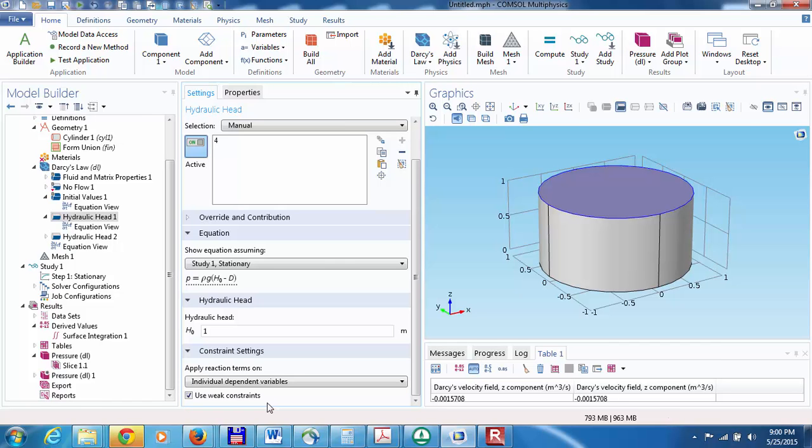On the equations that correspond to the nodes on the boundary where the value is specified to be a given hydraulic head, in this case 1.0, that equation really is not needed in the solution because it has a specified hydraulic head value. But within the discrete finite element equation associated with that particular node on the boundary, there is a term that is the net flux at that point. That net flux is the normal flux across the boundary.